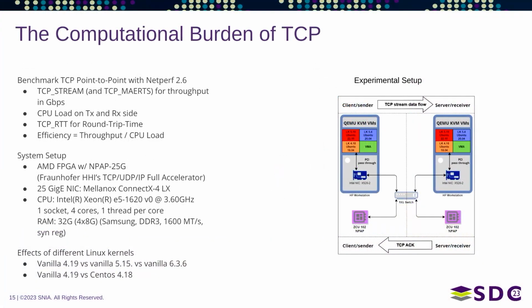The other aspect that we see is the pure computational burden of TCP. We're one of the guys who put TCP into a digital circuit. It's technology that we licensed from German Fraunhofer in Berlin. So we get repeat calls from users, engineers who run maybe an 800 megahertz ARM A9. They have a 10 gigabit Ethernet port, and they expect 10 gigabit of TCP transport, okay? And they're dead lucky if they get 2.5 gigabits, okay? Just line rate. That means TCP has a significant compute burden.